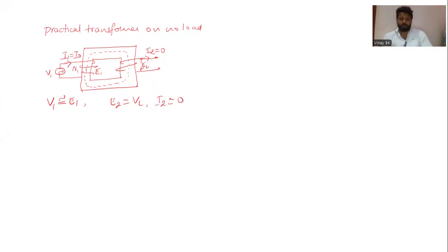Okay. So under no load condition, EMF E2 will be always same as supply voltage, as well as the flux that will be produced, you can refer it as phi. But under no load condition, what happened? There is a no load current I0. So this I0 or else no load current, you can also call it as I1. This I0 is having two main components. The first component is IC. You can call this as core loss component.